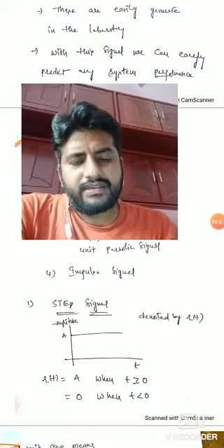So what are the instrumental errors? Those are percentage limiting error, guaranteed accuracy error, loading effect or loading error, and error due to aging. Aging means, if we keep using an already used instrument, definitely after some years it will reach an error because its lifetime is over. So then the expiry date of that instrument is over. So if you are doing the experiment with that instrument, definitely the instrument will reach an error.